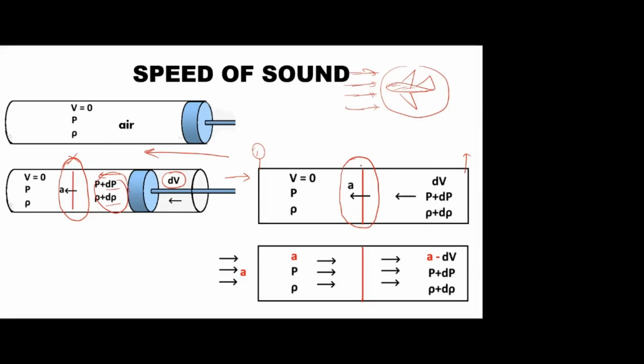So here also, with this moving wave, we cannot apply all the equations. So we have to make this moving wave stationary. So I imagine another control volume. There I am taking another flow which is opposite to this original flow condition with the velocity A.